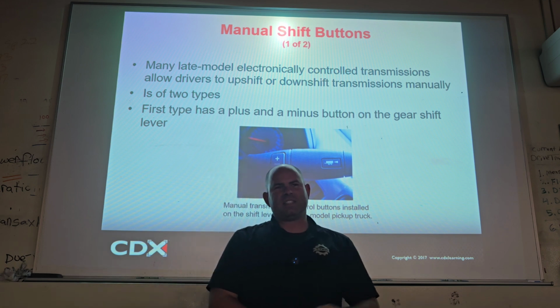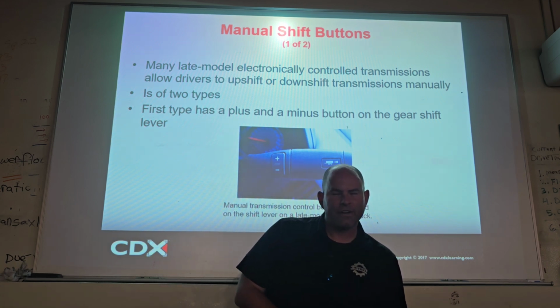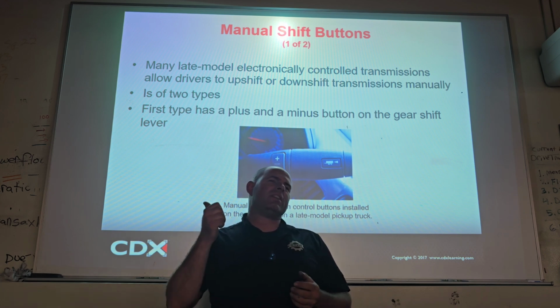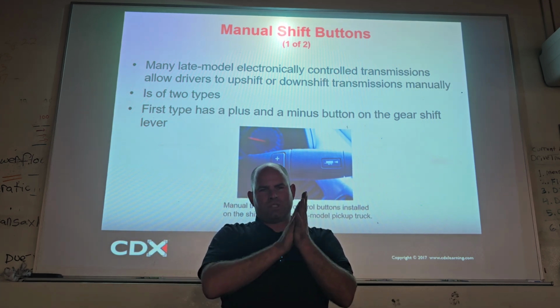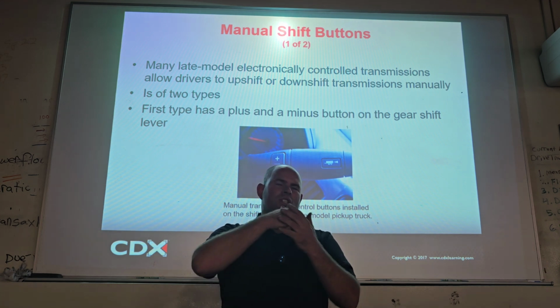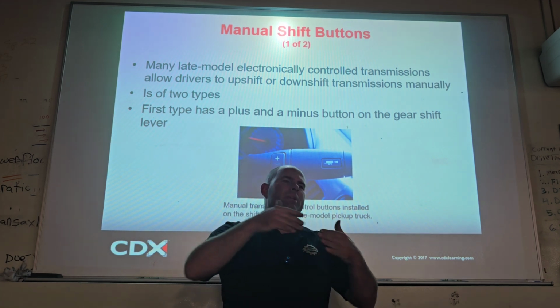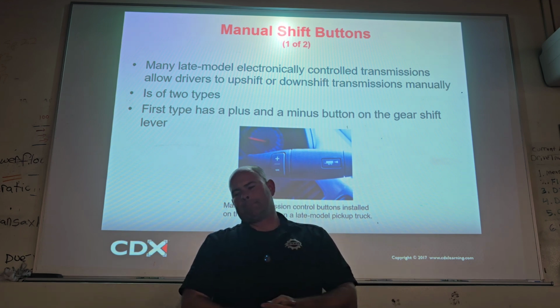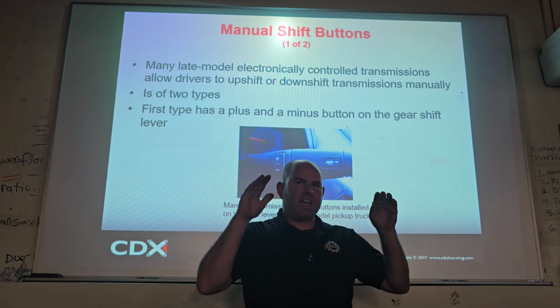All right. So let's say you get the Tundra and you want to haul another Toyota. You could put it in tow haul mode, increase the line pressure so your clutches don't slip, delay the shift timing so that way you're keeping the engine RPMs up and it's going to pull better. Cool? But also, let's say you crest the hill and you start to go down.